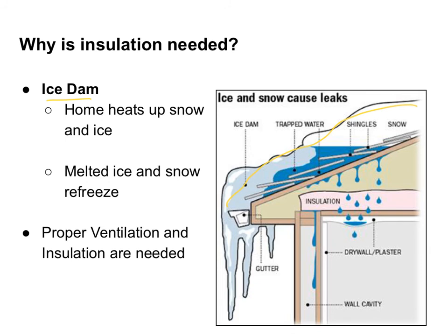The warm air in the attic causes the roof to warm and the snow to melt. So to fix this, you can increase ventilation, add insulation, and seal off every possible air leak that might be on that side of the roof. However, the best thing to do is to call a professional because in the long term it can damage your house.